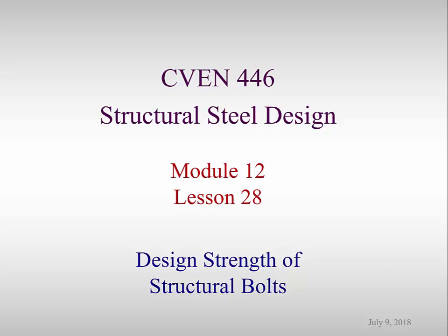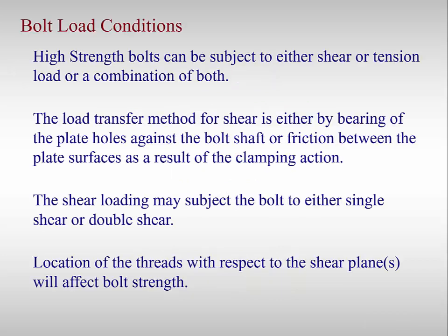Lesson 28 reviews the design strength of structural bolts. This includes both their shear and tensile strengths. Remember, the bolt is transferring a force or load between two elements of a connection. In structural steel connections, bolts can be subjected to either shear or tensile loads, or a combination of both.